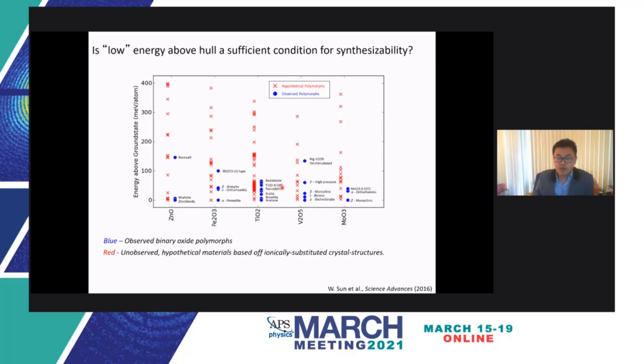The other phases that are known in TiO2 are high-pressure phases. So if you made a phase diagram for TiO2 with respect to temperature, pressure, and size, you would capture all the known TiO2 polymorphs. But maybe there are other axes that we haven't deliberately examined yet. Maybe, I don't know, oxygen chemical potential. With oxygen chemical potential, you can reach the Magnéli phases, like Ti5O9, Ti4O7. And so maybe there are other thermodynamic axes that can be used to synthesize other exotic TiO2 phases.